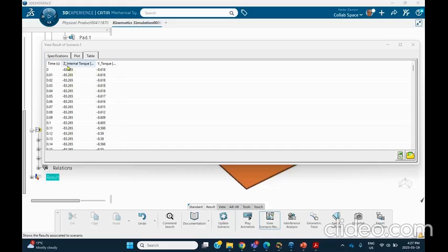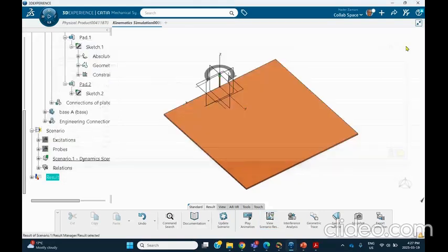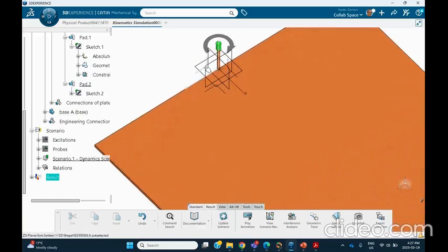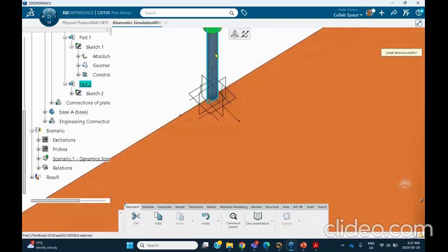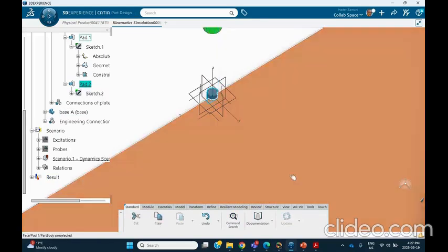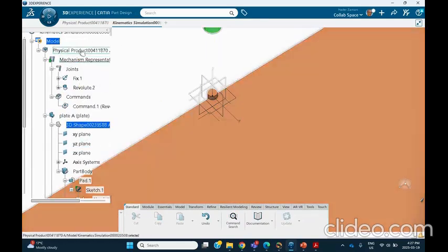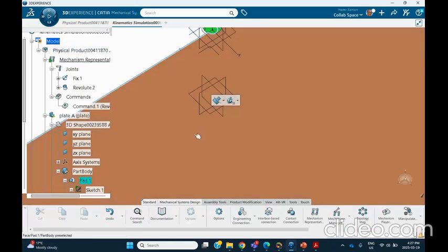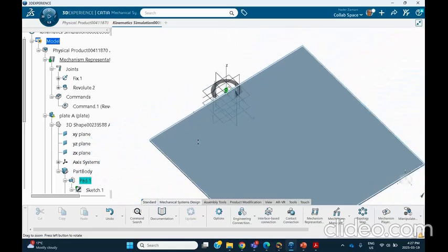Now, I don't particularly like the fact that these numbers, this column is not 0. This is okay. This is very close to what I have. Don't let the negative signs bother you, and I will let you know why later on. Now, my suspicion is that the reason that the Y torque is high, you're not getting what you expect 0, is this thing is too long. So what I'm going to do is I'm going to go to this pad, and instead of 20 millimeter, I make it 1 millimeter. Okay. And then we go back here, update the system, and we're going to run it again.